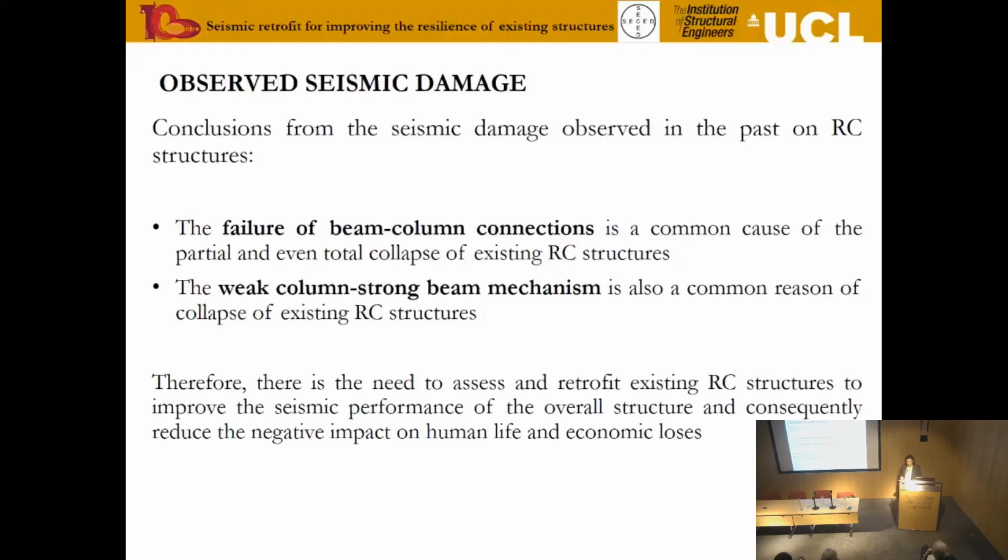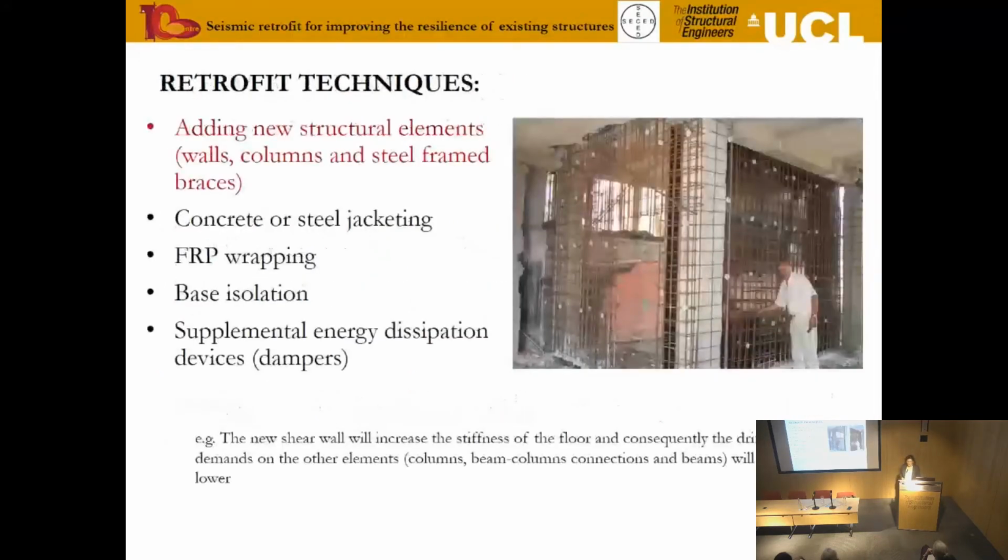Unlike masonry buildings, there are not so many constraints in terms of what you can do or what you can't do in a reinforced concrete structure. In fact, one of the most common retrofitting techniques is the addition of structural elements.